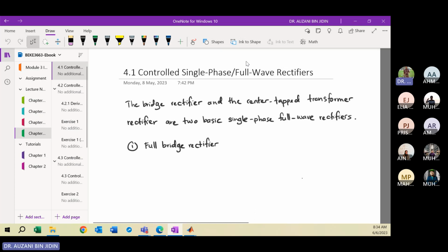You have already learned the rectifier for single phase, three phase, controlled and uncontrolled, and the operation of power switches. If you want to operate the converter as an uncontrolled rectifier, you have to use the diode, where you cannot control the switching operation, and it is based on the polarity of the voltage and current to turn on and off.